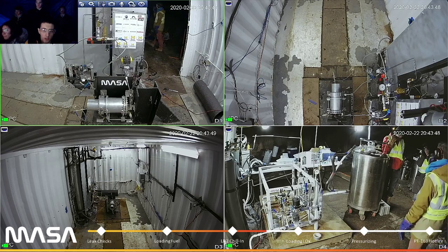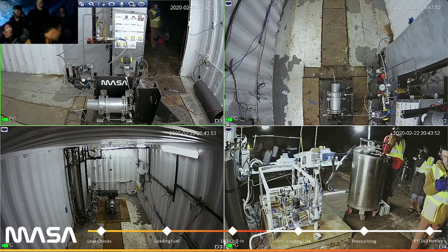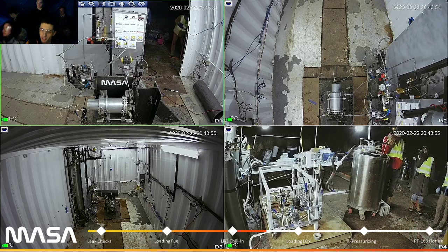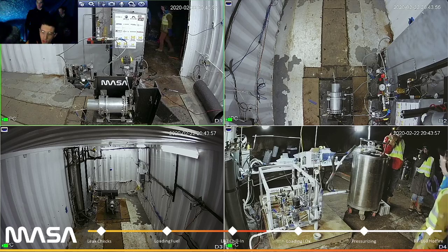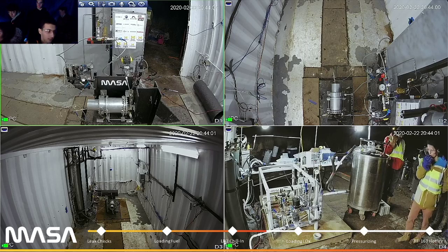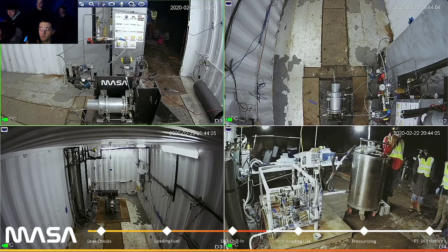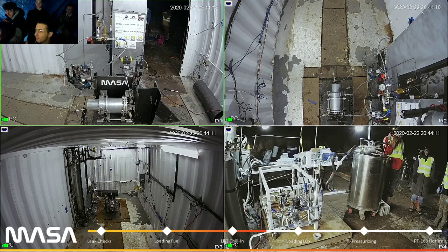Copy that. Closing locks. What's a motor? We don't have any motors here. We have an engine. We have a rocket engine. Oh, like do we chill the injector? No. We really only chill the liquid oxygen tank. Hold on, 20? Okay, copy that. Target tank pressure 20 psi in LOX tank. You're on fuel tank. LOX tank.